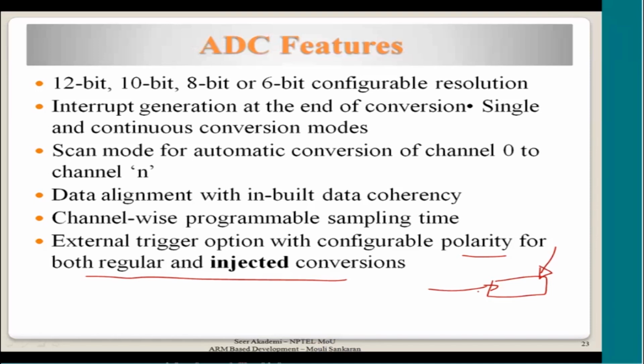Okay, so sampling is not done always. Suppose the motor speed is one data, and sensing the temperature of the motor is another. Suppose the speed is exceeding some limit, then maybe it is better to look at the temperature to see whether it is exceeding the allowed threshold value. Then you can control the speed, or you can send more coolant to cool down the motor. Some action can be taken, or you can inform the user that you are exceeding the allowed speed limit because the temperature is exceeding the threshold, and maybe if it goes beyond some point, switch off the motor